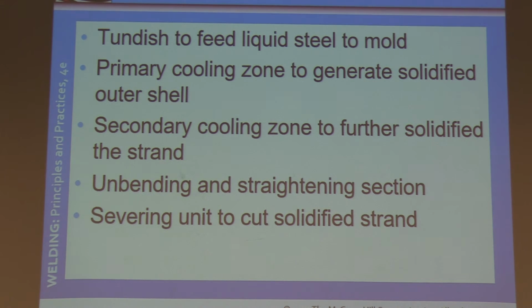So we're going to go to page 66 under solidification, casting and soaking of ingots. Right-hand column. If molten steel were to be cast into molds having the shape of the desired product, we would always be dealing with cast steel in our structures. Since cast steel is generally inferior to wrought steel, metal that is to be worked mechanically, the molten steel is poured into ingot molds or continuous casting and allowed to cool until solidified.